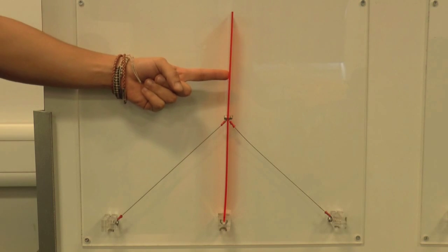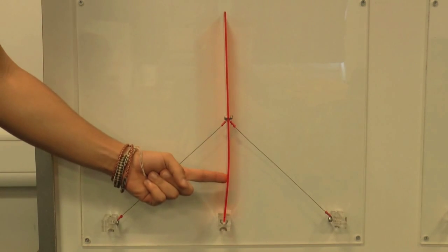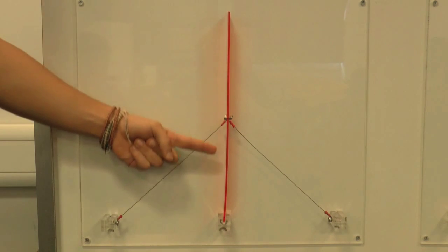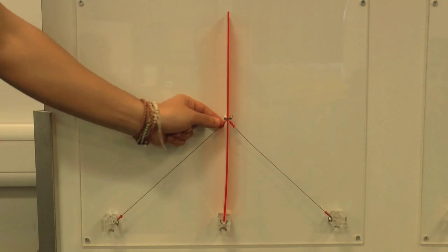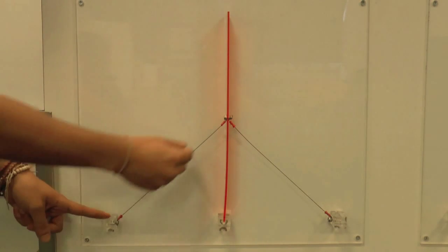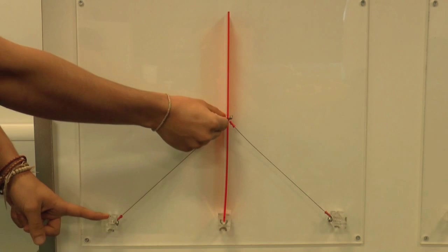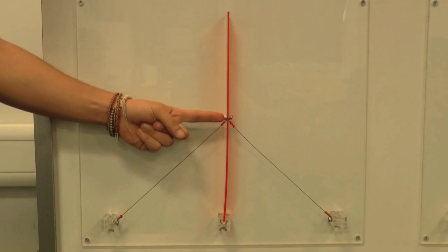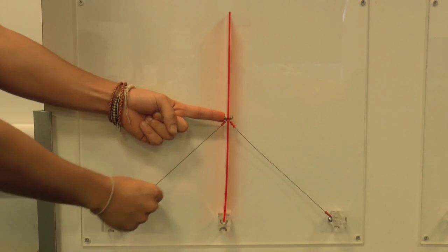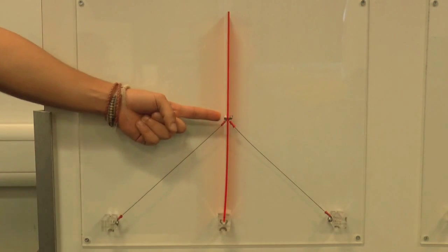Well, if I apply a horizontal force anywhere else, you can quite obviously see the deformation in the mast. And that's why the cables span between the end of one yard arm and the beginning of the yard arm above it. So any horizontal force is completely opposed by the horizontal component of the force in the cable.